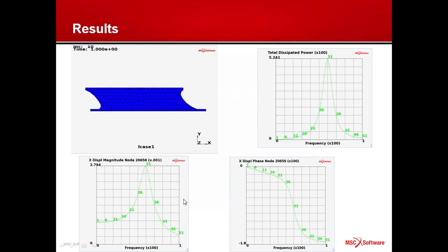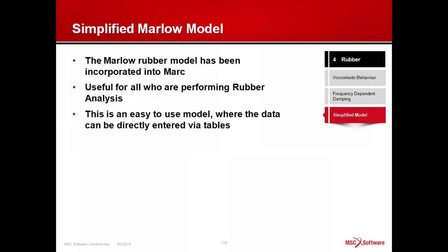And then after doing the excitation here between 0 and 100 hertz, we would have looked at the displacement as a function of the frequency, the phase angle as a function of the frequency, and the amount of dissipated energy or the dissipated power as a function of frequency.